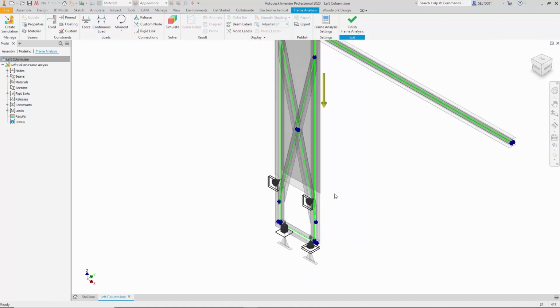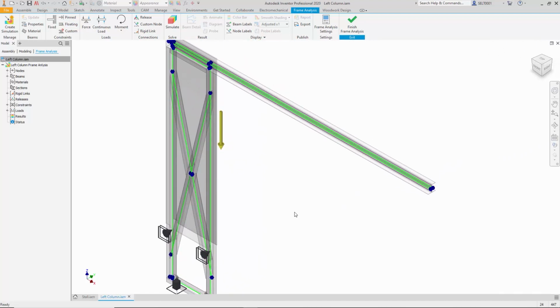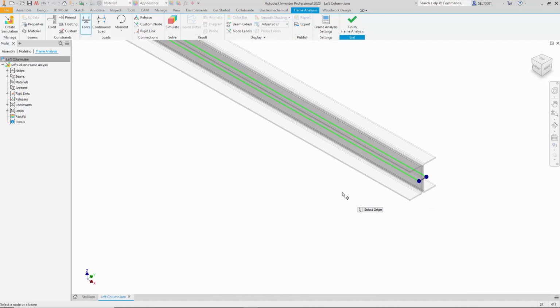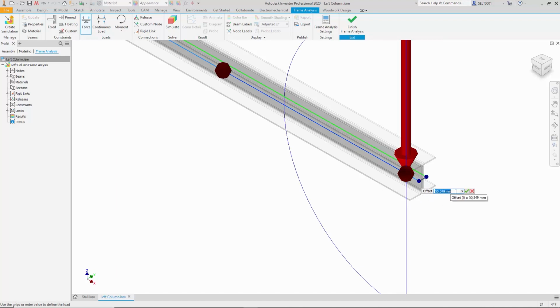Which affect this construction, where we know that 4 points are spread over 4 points, 25 kilograms each, and here we have 2 beams, which are 25 kilograms. At the point, they divide into 2 loads. This works out to 12.5 kilograms or 125 newtons.